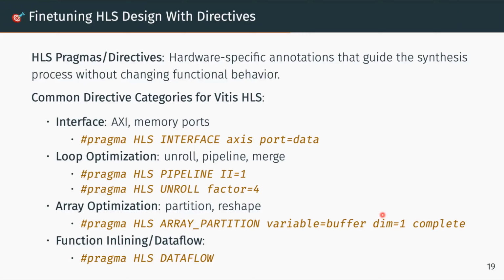But if you partition it, so each part is implemented on its own RAM, then you can access it easily. So this needs to be considered in design. Sometimes you may not notice what constraint is keeping your loop from being pipelined. This might be the reason, because you can't really access the data.